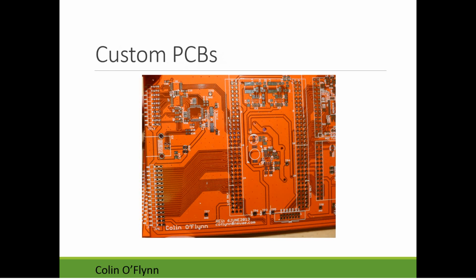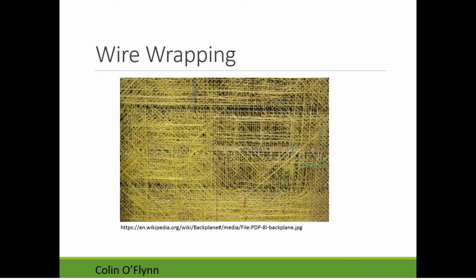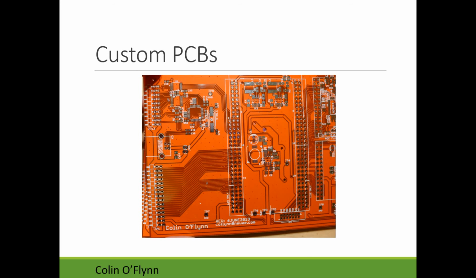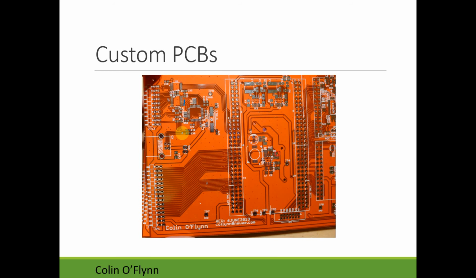So instead of that, when you go to design, you say, okay, I've done some breadboarding, I've got a pretty good idea this is going to work, and I'm going to lay out a circuit board. And you can do a fairly basic board like this. This is a combination of through-hole parts, like connectors at the edges here, and surface mount, which I mentioned. These parts would not fit in a breadboard because they don't actually physically have leads that go down anywhere. You can sort of see this outline here. There's no holes here, so the part itself solders right on that.